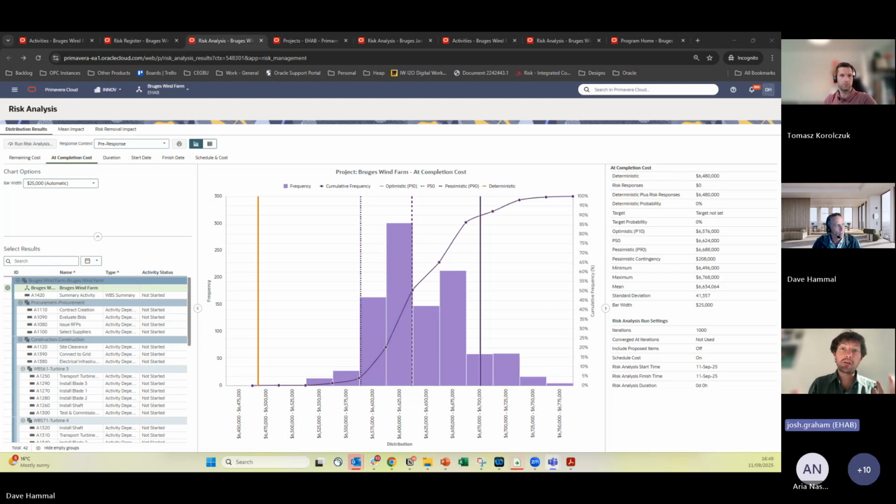And of course, whether your site is flooded or waterlogged or not is obviously dependent on the soil type and the amount of drainage that you can have. So we are building what we're calling a wetness model, which basically combines soil type, and therefore drainage, with the preceding number of days and what the cumulative rainfall is on any given day.